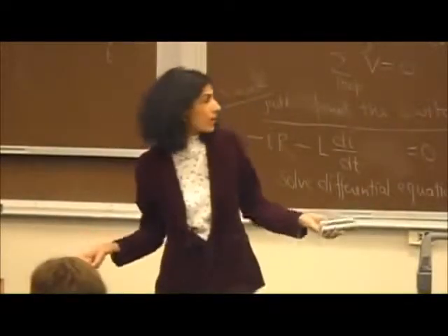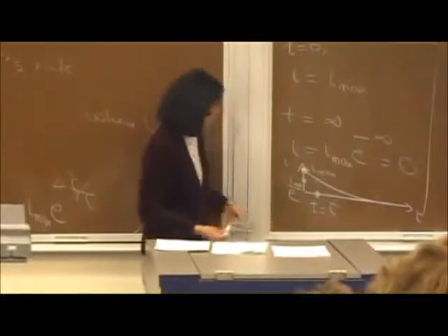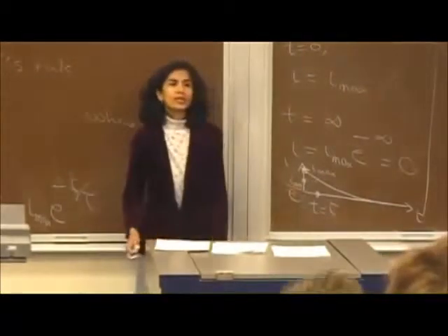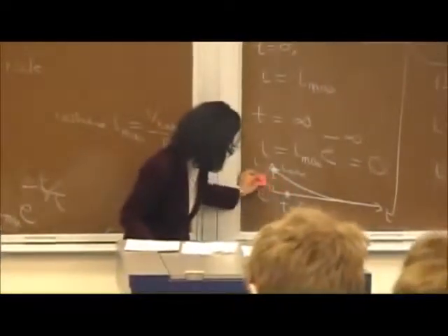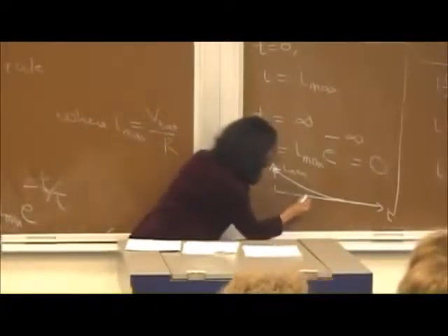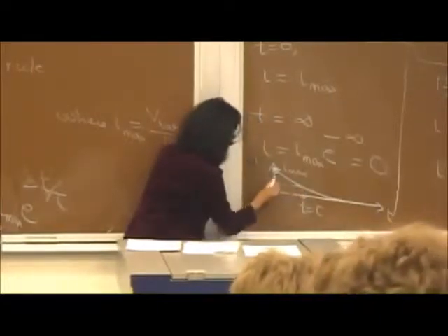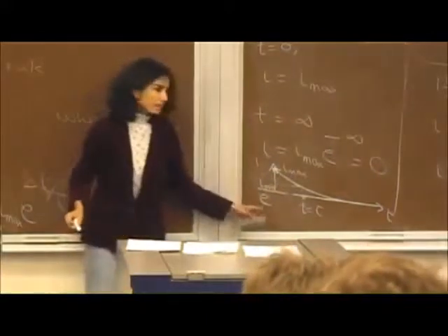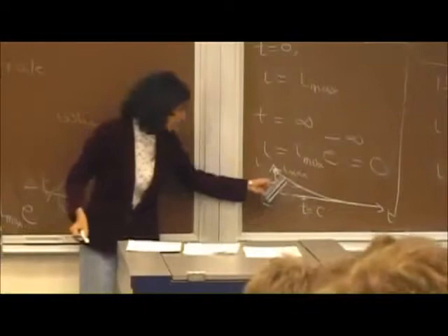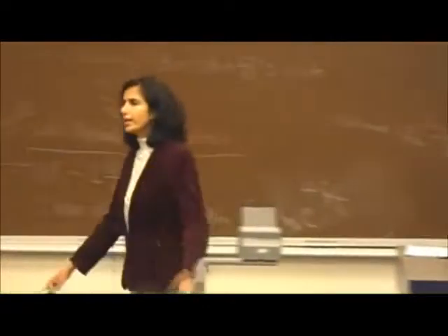So basically it's 2.71. And so the point is that t is equal to tau corresponds to that time where the current would have decreased by a factor 2.71 of its maximum value. In fact, this plot is not showing that very well, so maybe I should choose it somewhere over here. So t is equal to tau is the time when the current has decreased to I max divided by E. E, remember, is 2.71, which is almost 3. So it's become I max divided by 3 roughly. It decreases by a factor of 3 compared to the maximum value. Any questions, folks?